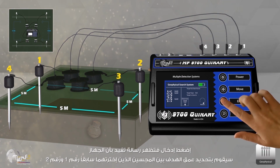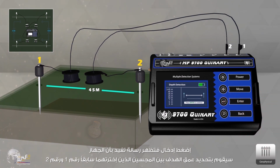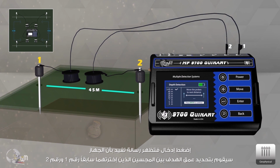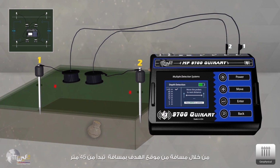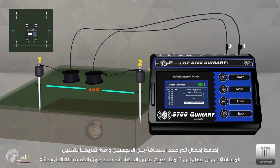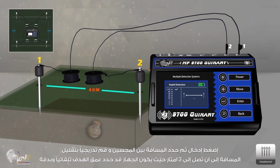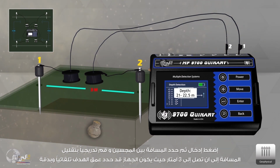Press Enter and a message appears stating that the device will determine the depth of the target using the two probes, number 1 and number 2, at a distance from the target's location starting at 45 meters. Press Enter and then determine the distance between the two probes, and do so gradually by reducing the distance to 3 meters, and then the device displays the depth automatically and accurately.